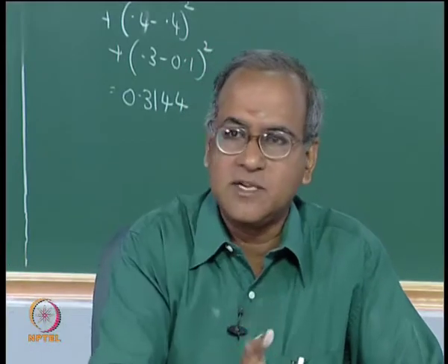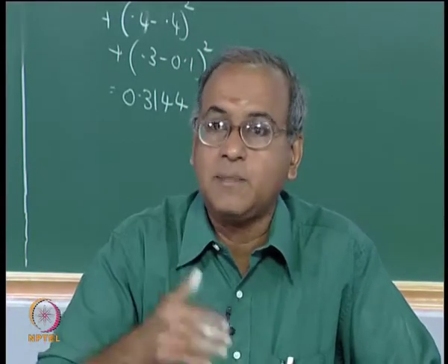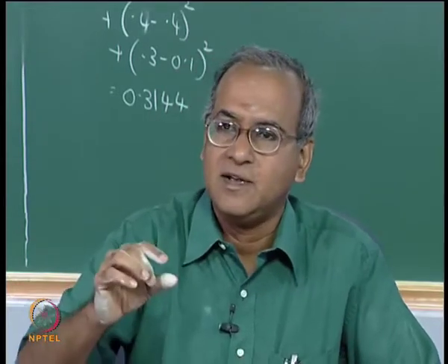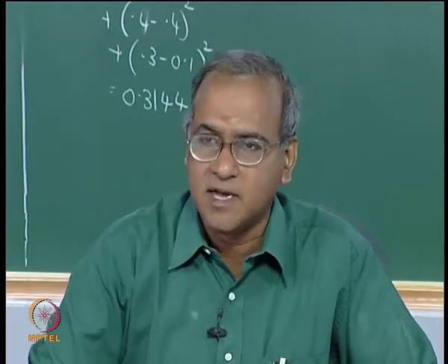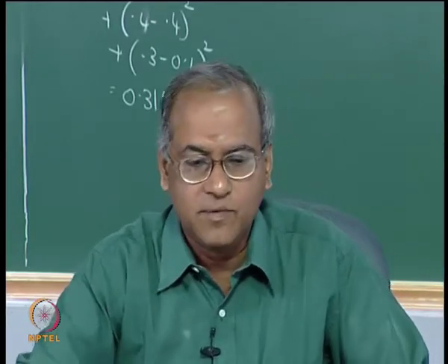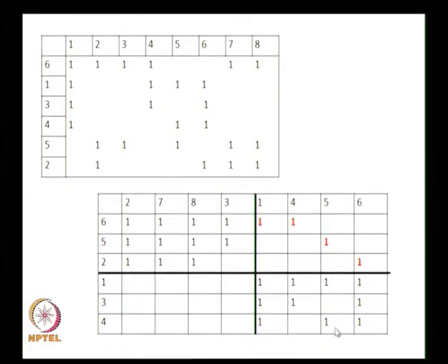So, an older machine which is already there might be capable of doing it. So, one needs to check this, sometimes even at slightly higher processing times, and at that point we understand that if machine 3 can do this operation at higher processing time, it is still all right to do it within the cell rather than send it outside to another cell. So, the first aspect of alternate machines is taken care of this way.